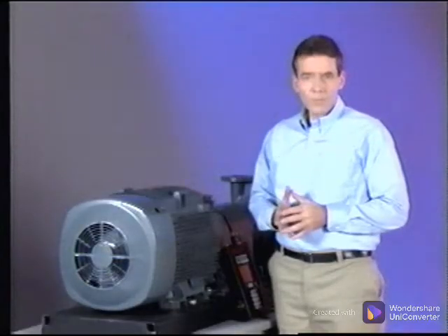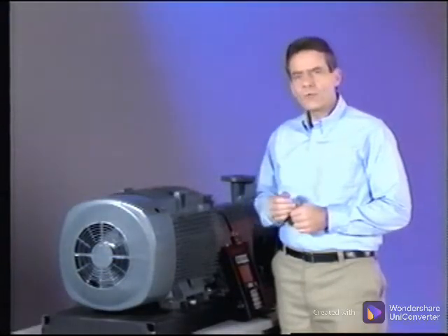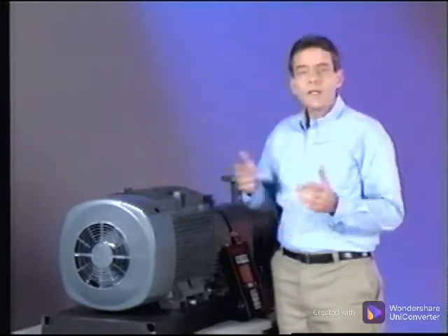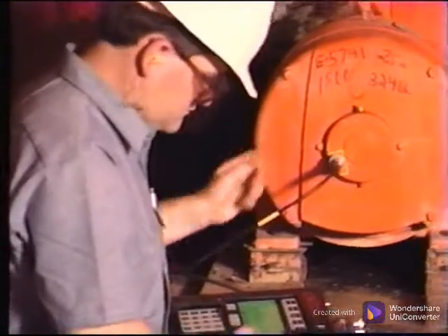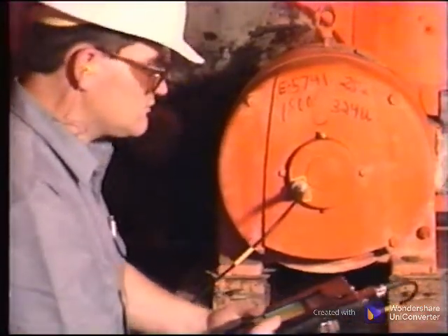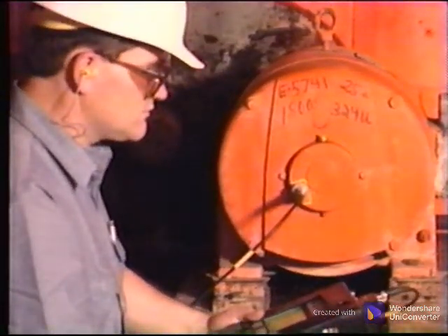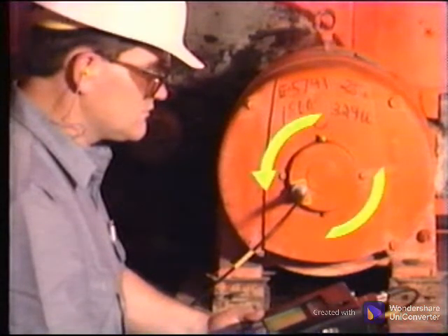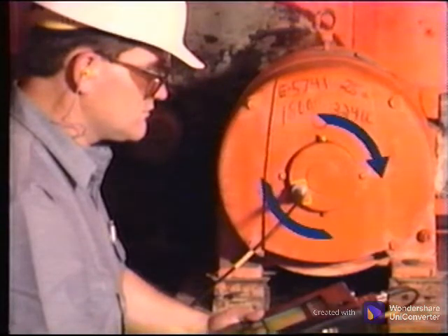The analysis equipment is so precise that even minute differences from one side to the other can significantly alter the data. The best place for an axial measurement is near the shaft center and on the bearing in the load zone. The load zone is the radial direction in which the most force is applied during normal operation. In horizontal machines, this is usually in a clock face position of 4 to 5 o'clock or 7 to 8 o'clock, depending on the direction of rotation.